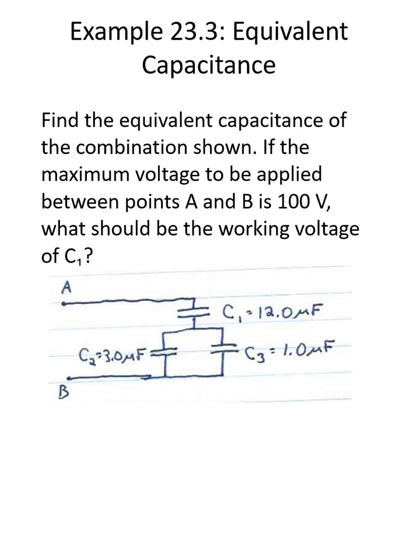You see that the two on the bottom, capacitor 2 and capacitor 3, are in parallel with each other, and they will mathematically obey the rules of parallel capacitors. What we're going to do is combine them and pretend that they're one equivalent capacitance, right where my red marker is. It's a fictitious capacitor that we're going to mentally replace these two with. I'm going to call it capacitor 2,3 because it's a combination of 2 and 3. Well, capacitor 2,3 is in series with C1.